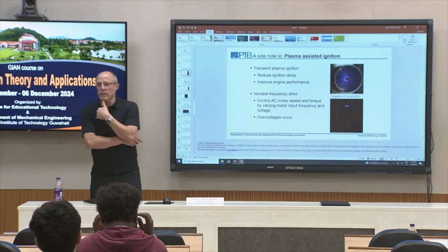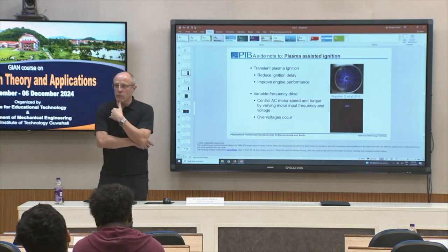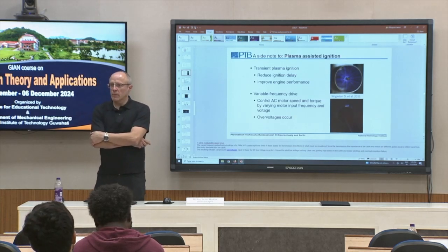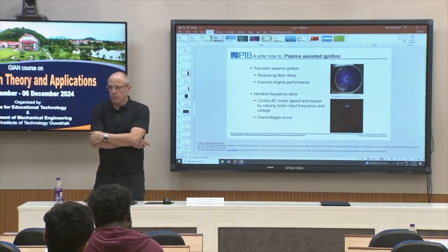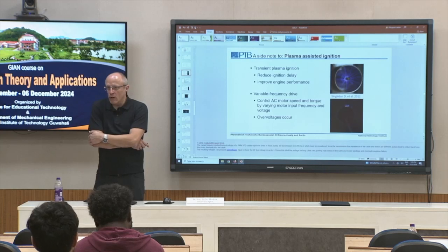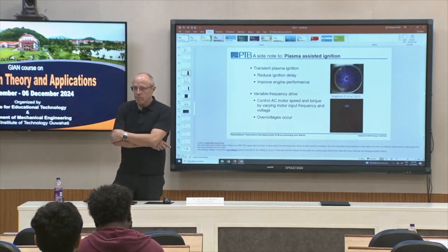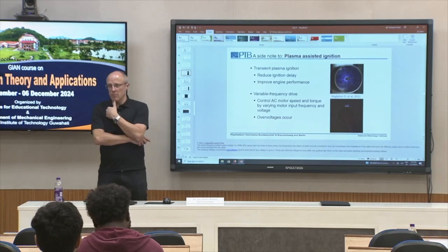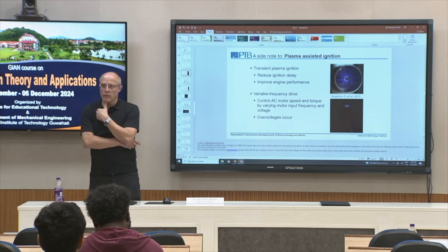You have also an additional effect. You do not need to know only when ignition occurs. You also have to consider the pressure rise, so how fast the combustion takes place. This is what you see also in your pressure curve, dp by d theta, the rate of pressure rise, the second important factor. And the question is how to filter this. I have no proper answer.